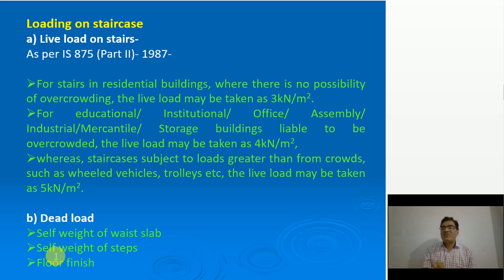So sec phi is equal to under root of R square plus T square divided by T. What is this? R means rise, T means tread. That means we are converting the load on the inclined portion to the load on the horizontal portion. Fine, that's why sec phi is to be considered.